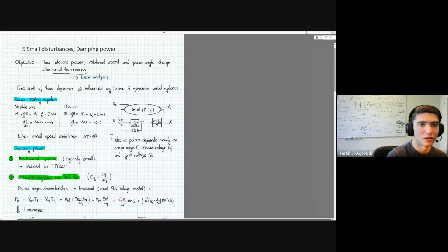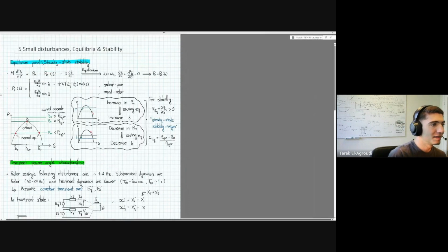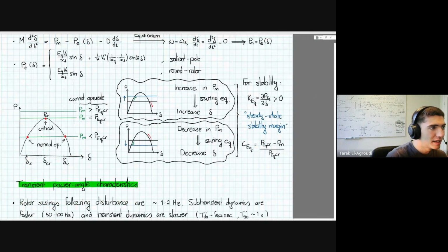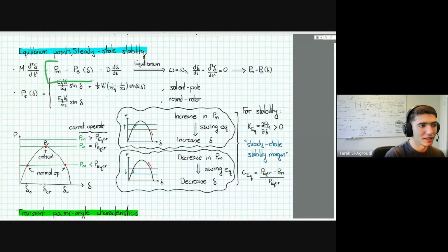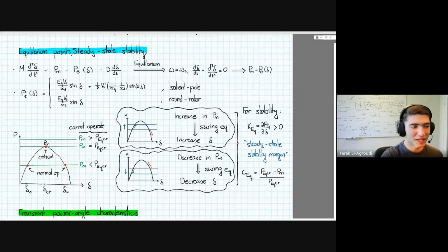So knowing that, how would you do some analysis here? Just some graphical intuition first. The swing equation is driven by the power imbalance between the mechanical and the electrical power. The mechanical power can be viewed as fairly constant for the time frame in consideration. As a reference already, the frequency control part of the control of generators, it moves this mechanical power. So that's how it works. But more about that later, I guess.